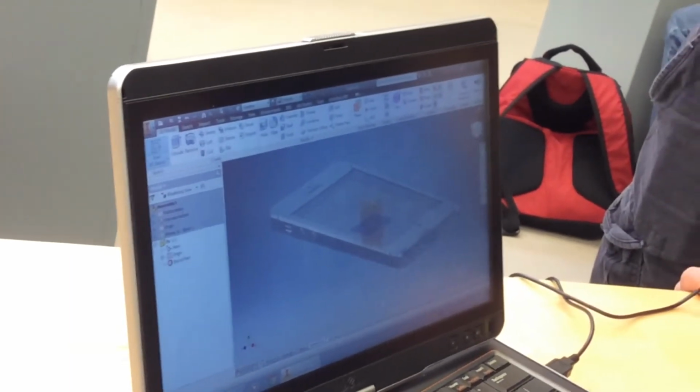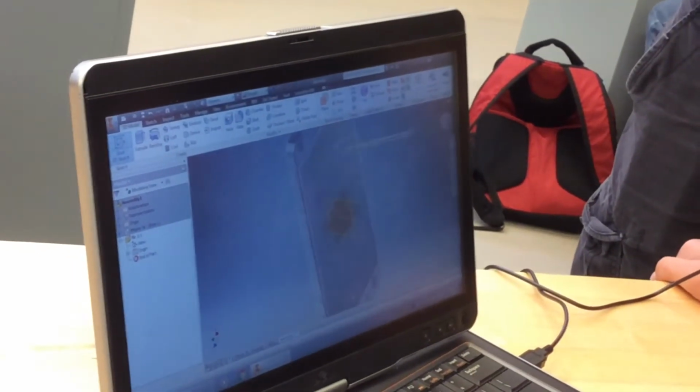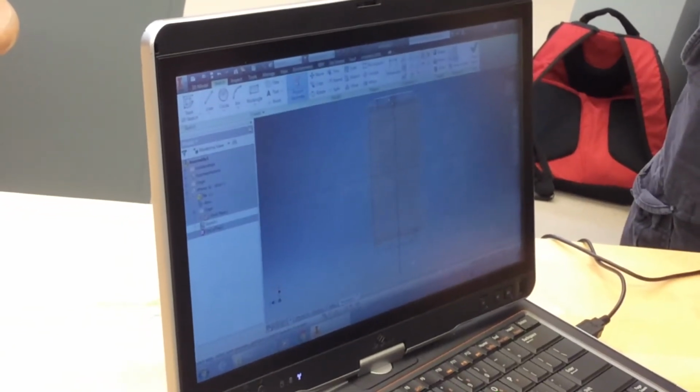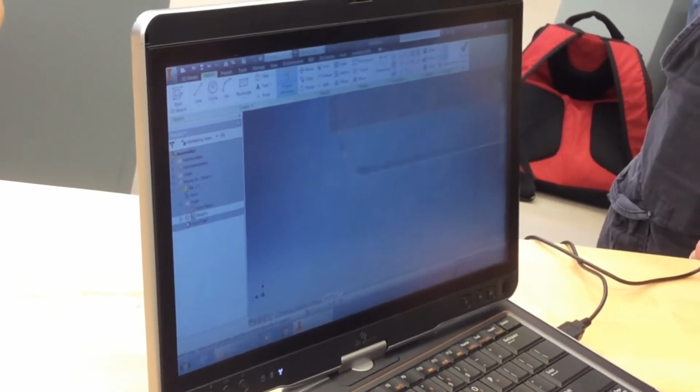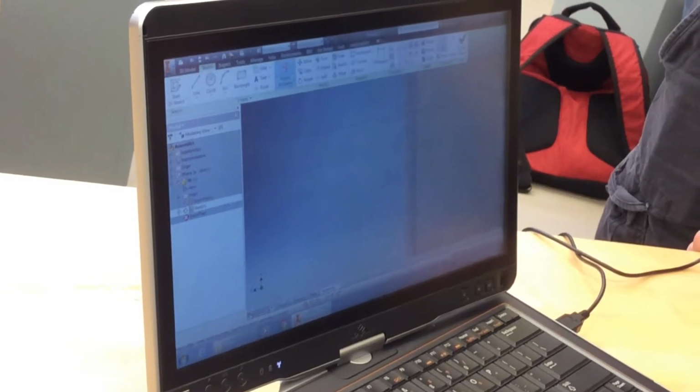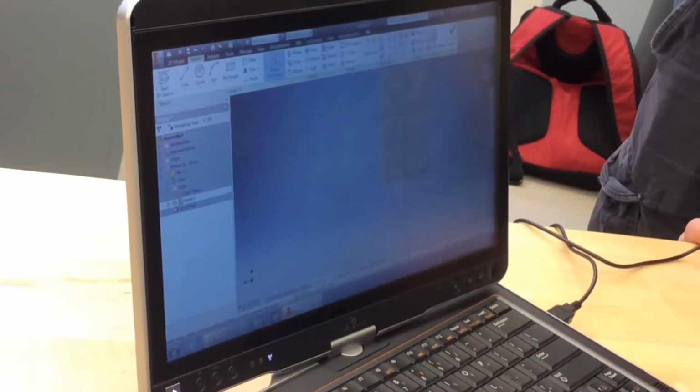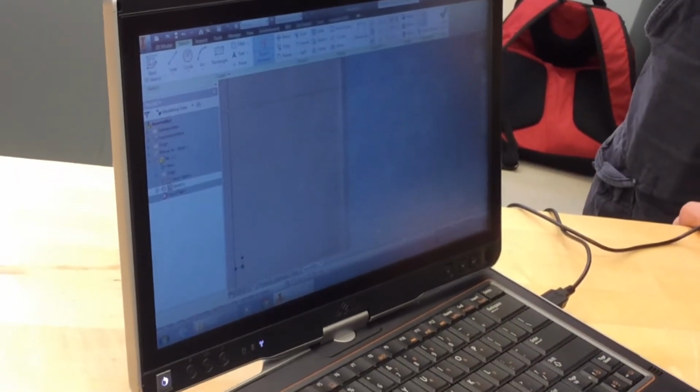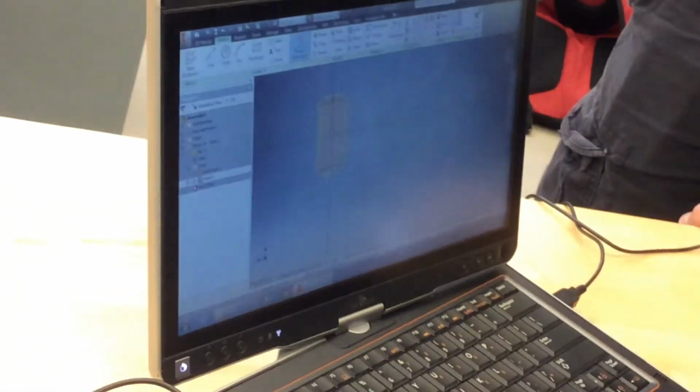I have to start a 2D sketch, and again, just go off the back of the phone, mainly just for consistency's sake. So here we go, at the back of the phone. What I want to do now is project the geometry of the outside of the phone. So, of the very outside edges. 1, 2, 3, 4, okay? Also, if I want to cut the camera out at this time, I can, and do that in